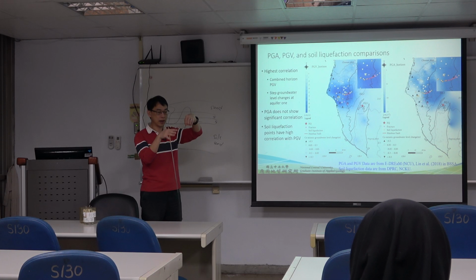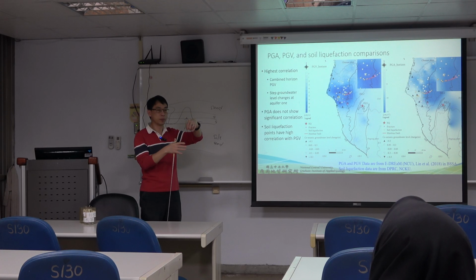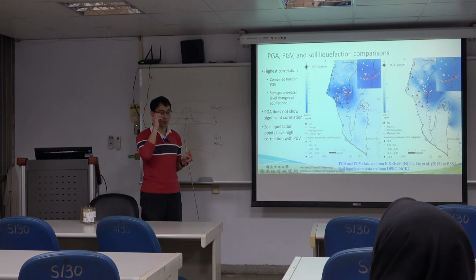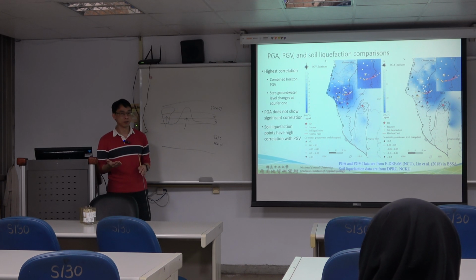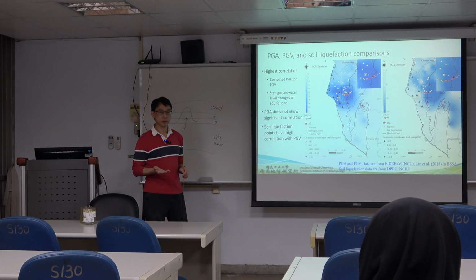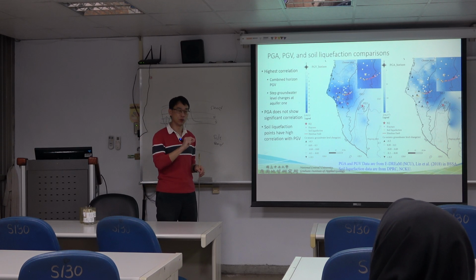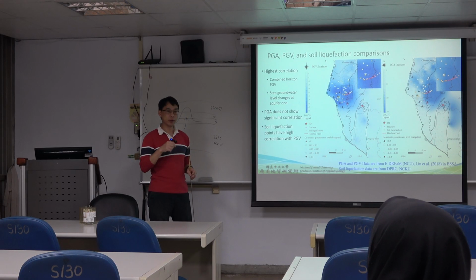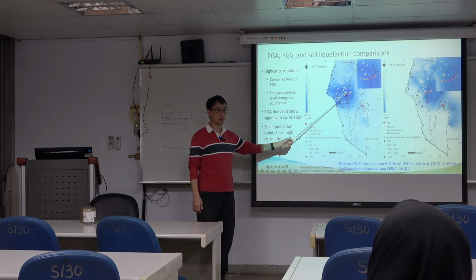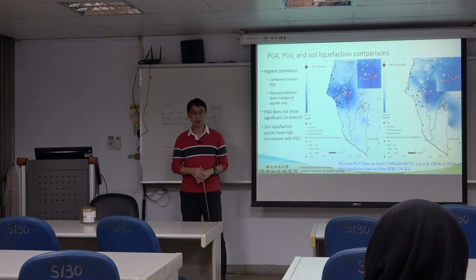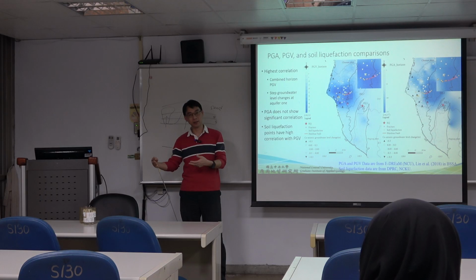So if this area has high water pressure increase, it might become like a soft material, and it might attenuate or weaken your energy. Another possibility is that liquid is not able to bear shear waves, so it will dampen the high frequency and only keep the low frequency. So when we observe the PGV here is high, it could also be due to the material being affected. So they have interactions, not just one way.